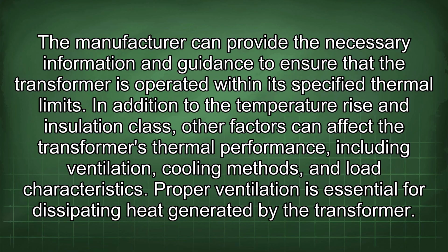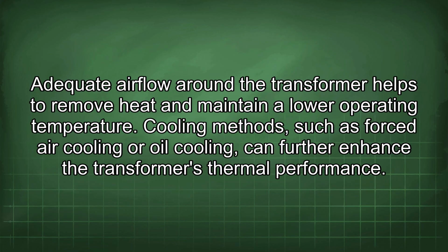limits. In addition to the temperature rise and insulation class, other factors can affect the transformer's thermal performance, including ventilation, cooling methods, and load characteristics. Proper ventilation is essential for dissipating heat generated by the transformer. Adequate airflow around the transformer helps to remove heat and maintain a lower operating temperature.